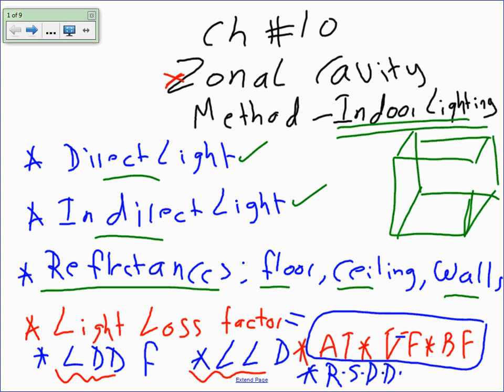If you guys go to page 83, you have to take into consideration the ambient temperature. Fixtures love to work at a certain temperature. You go higher or lower than their ambient temperature, they will lose lumens. So ambient temperature, there's the ballast factor, they say BF. So ambient temperature is 80. Everybody can see the 80 is ambient temperature. BF is a ballast factor. Poor ballast or good ballast and so forth.